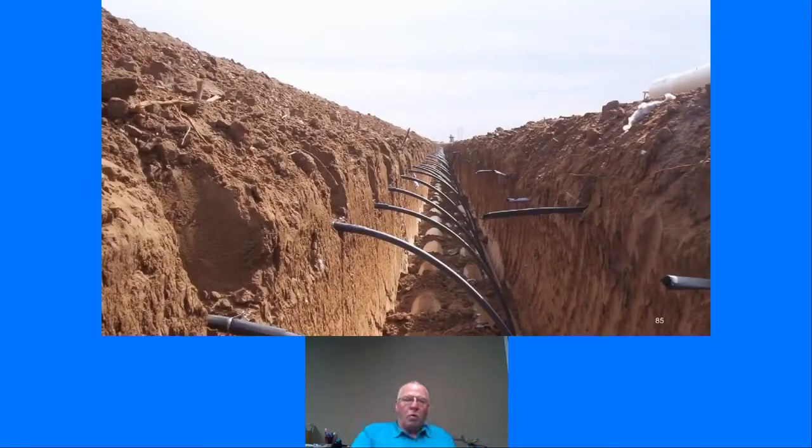You also want, when you're making these connections, to make sure that the riser tubes are uniform. You can look down this trench and see how uniform they are. None of those riser tubes rise above the depth of the dripper line. That ensures that we don't have a bunch of shallow tapes there on the end of the field that can be damaged in our tillage practices.